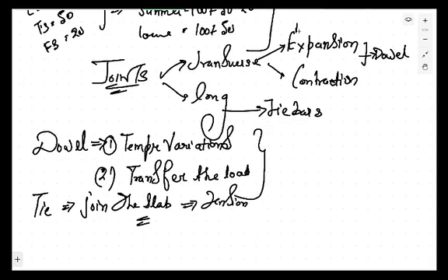The expansion joints have a maximum spacing of 140 meters. The contraction joints have a maximum spacing of 4.5 meters if they are unreinforced, and 14 meters if they are reinforced. अगर reinforced slab है तो contraction joint का maximum spacing 14 meter है. If unreinforced, then the spacing is 4.5 meters. Also, the maximum spacing for expansion joint is 140 meters.